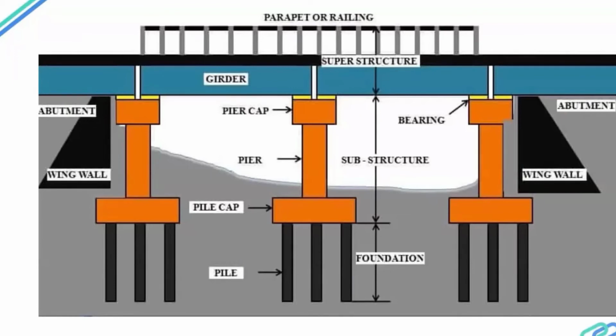see here a schematic diagram of the typical structural arrangement that we follow in the metro viaducts. So going from top to bottom, we see there are railings, and then we have a girder, which is known as a superstructure. Superstructure is basically the part on which the metro train actually runs, which takes the load of the metro directly. There are rails which are fixed on this superstructure, on this girder, and on those rails the metro plies.